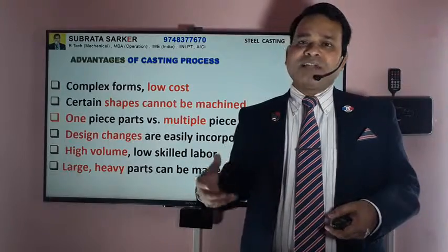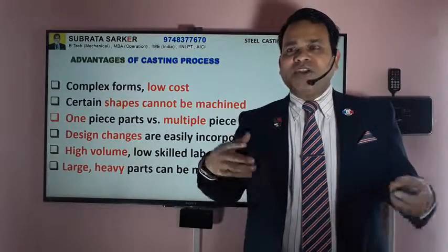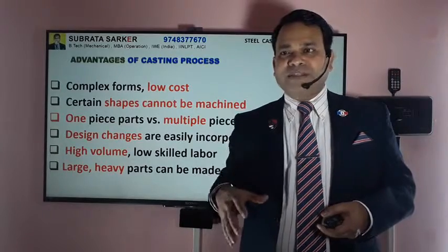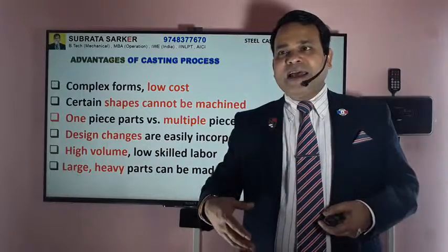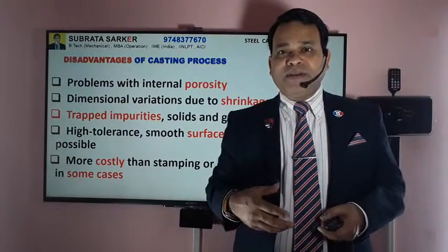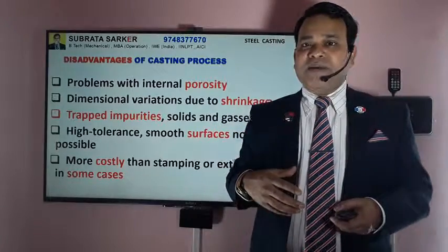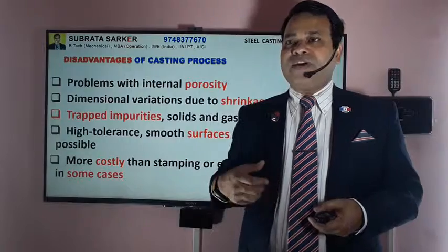Material may get rejected. In some cases where you need a very good surface finish, you will not get it through the casting process; casting has a limitation. By machining you may get this. In some cases making castings is also very costly depending on a lot of parameters, so there may be alternative processes by which you can get an optimum manufacturing cost.